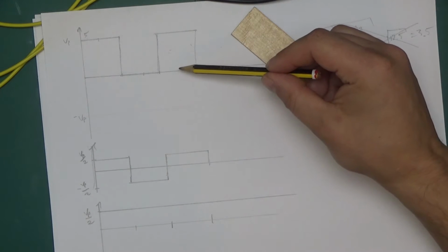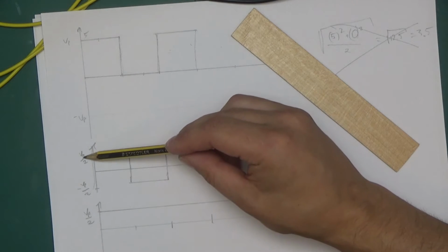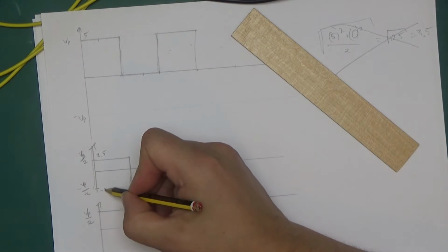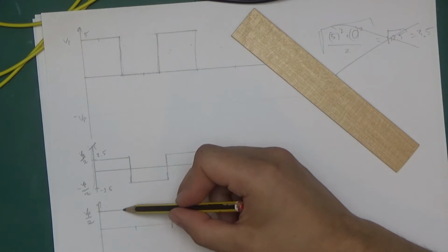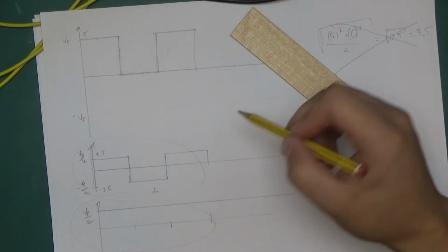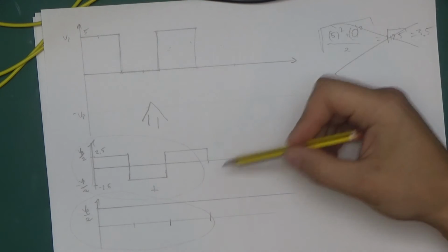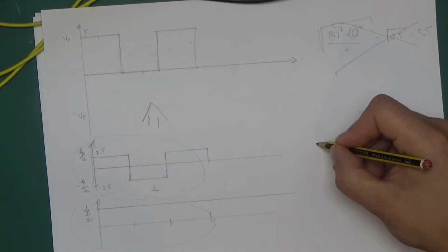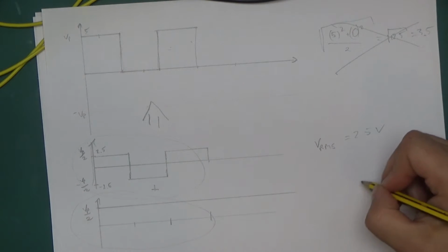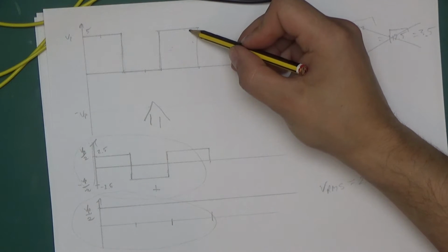Positive square wave can be considered as a symmetrical square wave of half the peak value. So in this case, voltage peak over 2, so if this was 5, this will be 2.5 volts and minus 2.5 volts, combined with a DC offset of 2.5 volts. 2.5 volts added to this square wave will produce that. When we combine those two, we know that this would be RMS value 2.5 volts, and this is 2.5 volts DC, so that's also 2.5 volts. Now, if we add those two together, we'll get 5 volts, which will not be the RMS value of this. It simply cannot be.